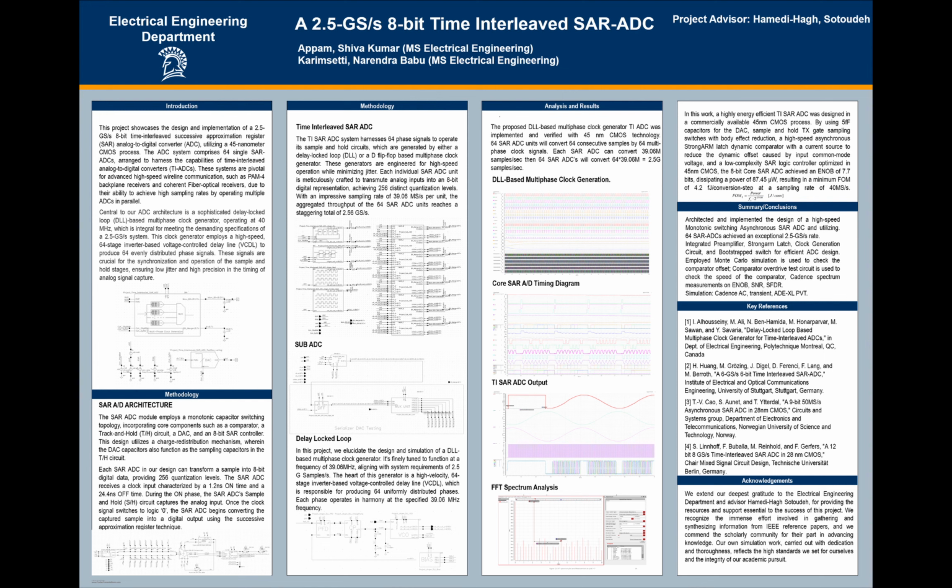First I want to explain the core ADC structure, which is the main building block of the time interleaved SAR ADC. In this core ADC structure we have a sample and hold block, then a capacitor array, a comparator, a clock generator, and the SAR control block and the feedback loop.